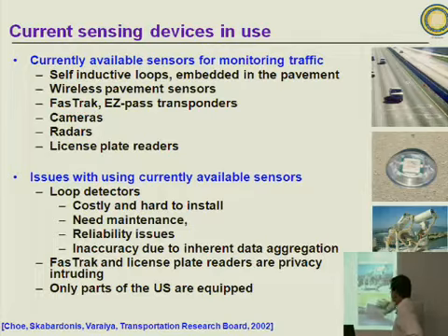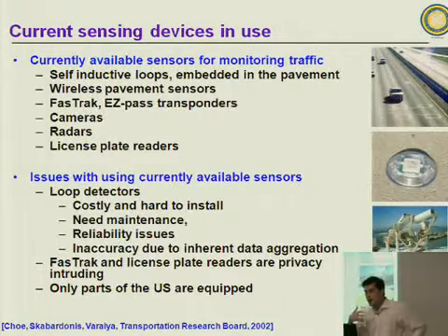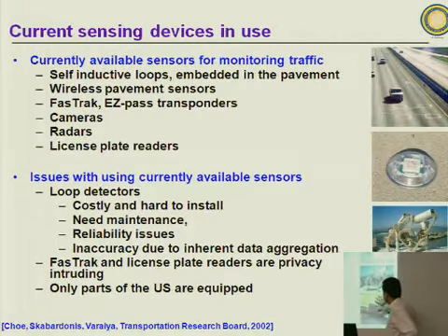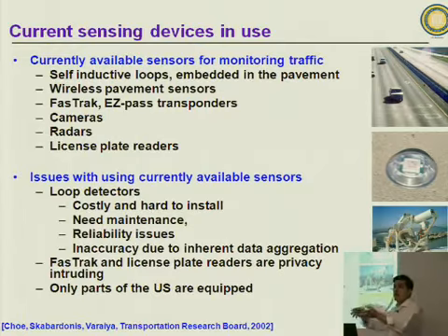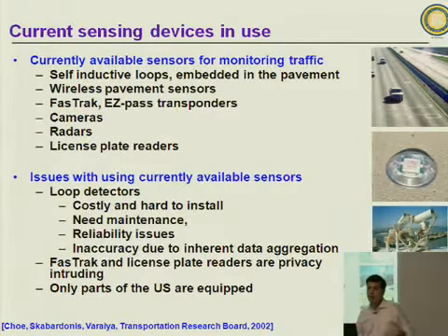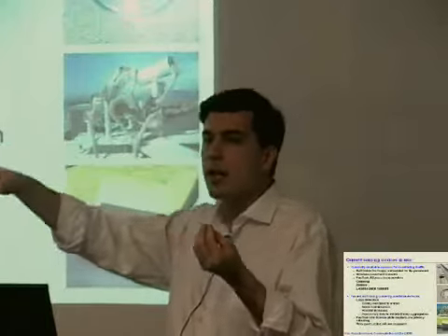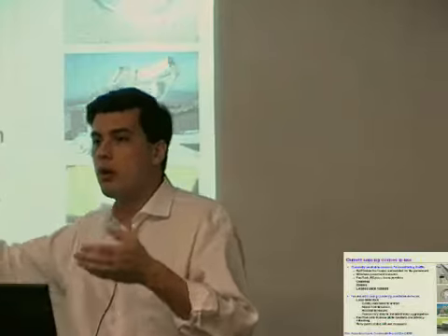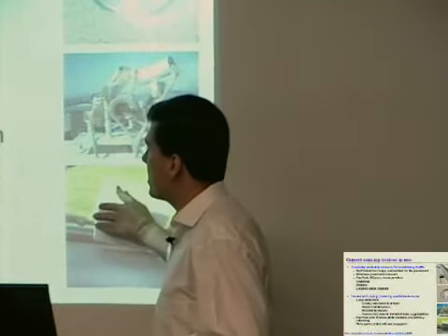There is also more recent technology used for specific locations. Camera data is fairly common and provides high-accuracy traffic data. In specific places like the Bay Area or on the East Coast with EZ Pass, you have RFID transponders that travel on board cars and check in at several locations on the highway beyond the toll, and therefore provide traveler information.